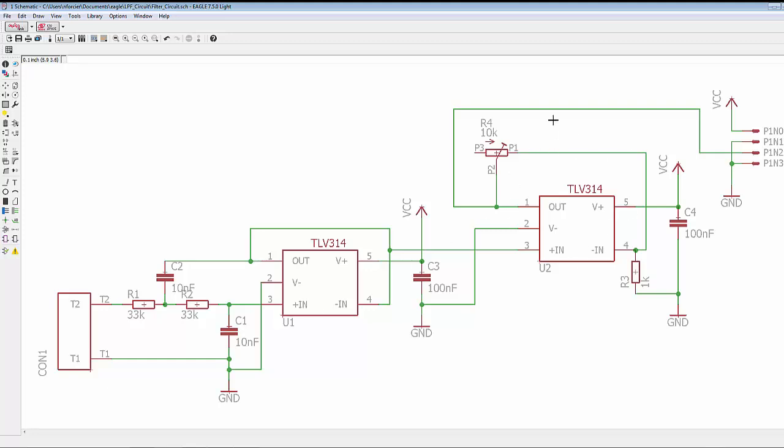Here's my amplifier circuit. The resistor in the feedback loop is a variable resistor, so we can adjust our gain. Here's the other resistor, and once again, I tied this to a bypass cap to reduce noise. And then I just have standard pins, or pinholes, I should say, with 0.1 inch or 2.54 millimeter spacing. So that's what will feed to our ADC circuit. Now, I should mention, normally you probably would have this on your main circuit. Just for this tutorial and example purposes, I'm having this on a separate small PCB board. Okay, let's look at the actual PCB layout.